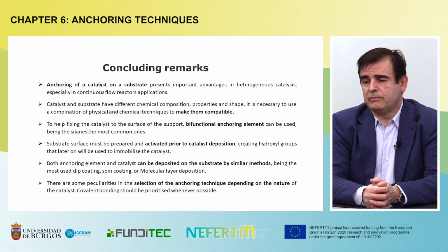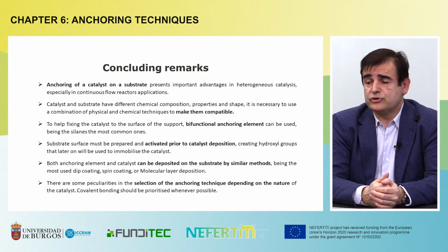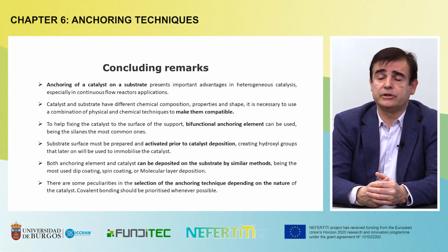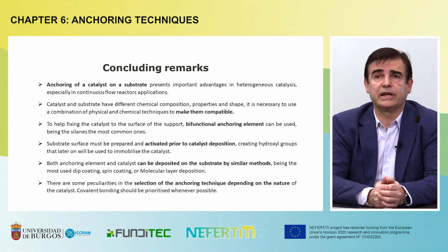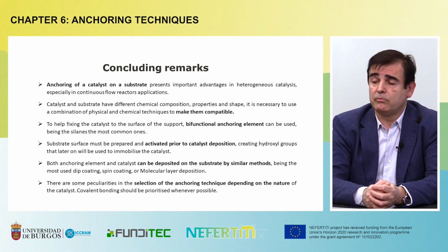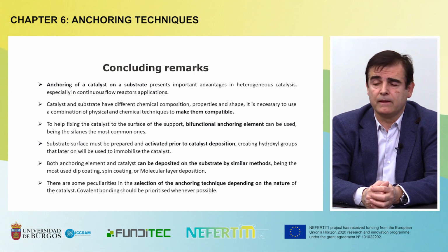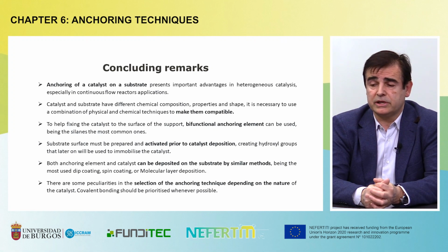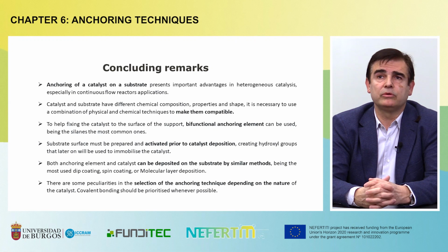We can finish this chapter with some concluding remarks. Anchoring of a catalyst on a substrate presents important advantages in heterogeneous catalysis, especially in continuous flow reactor applications. As the catalysts and substrates have different chemical composition, properties, and shape, it is necessary to use a combination of physical and chemical techniques to make them compatible. To help fix the catalyst to the surface of the supports, bifunctional anchoring elements can be used, silanes being the most common ones.